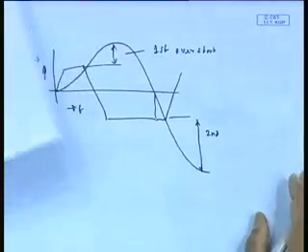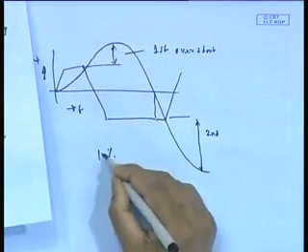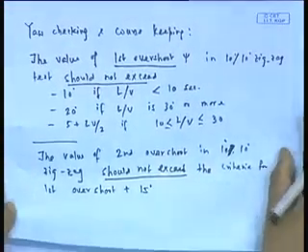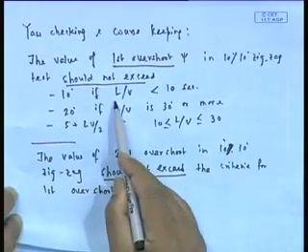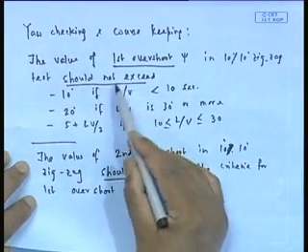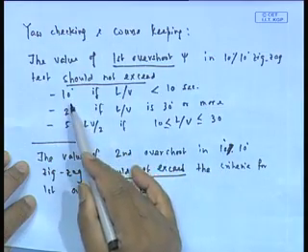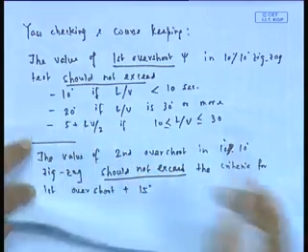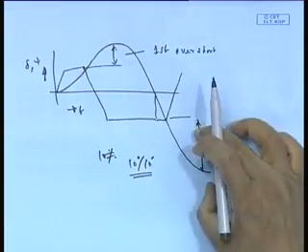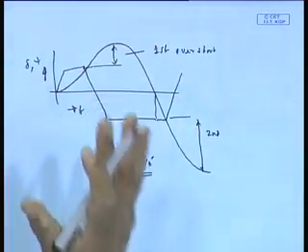Why am I telling you this? In a 10-10 maneuver, a 10-degree zigzag, it puts a limit based on, of course, L by V. That means there is a dependence on length and speed, by which it says that I must have a limitation on my first overshoot. It cannot be more than some value. And for the second there is also a limitation, that is this plus 15. That means the rule has put a limitation on the overshoot angle. It cannot exceed more, again for safety, so that you make sure that your ship is safe.